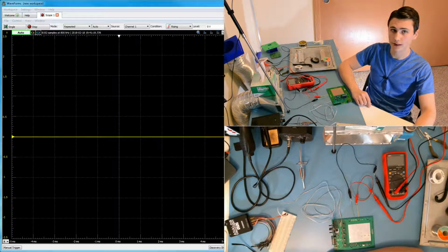When it comes to the time domain and frequency domain measurements that require an oscilloscope, we will measure the voltage across the 0.3 ohm shunt resistor in series with each set of LEDs to measure the current. We can use Ohm's law, volts equals current times resistance, to translate this voltage and resistance into a current measurement.